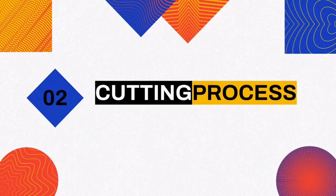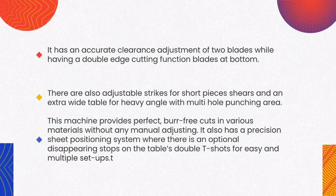The next part will be about the cutting process. The cutting process is where excess material is removed by shearing from a preformed blank in the form of chips using a wedge-shaped cutting tool in order to get the desired shape, finish, and tolerance. The cutting process can also be done on other materials such as plastics, woods, ceramics, and so on.